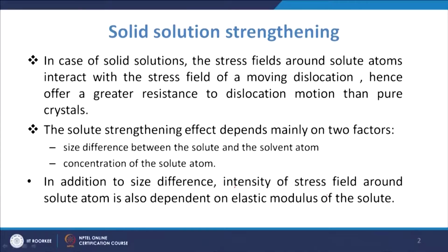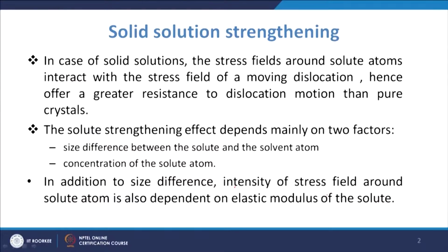When we talk about solute strengthening, the effect depends mainly on two factors. One is the size difference between the solute and the solvent atom. There may be a size difference between them, and that will affect the strengthening effect. And second is the concentration of the solute atom. These two factors are important.